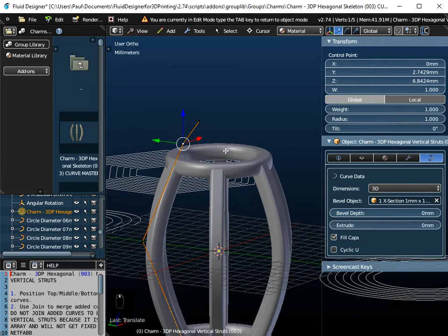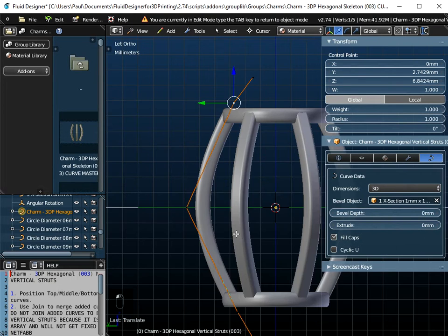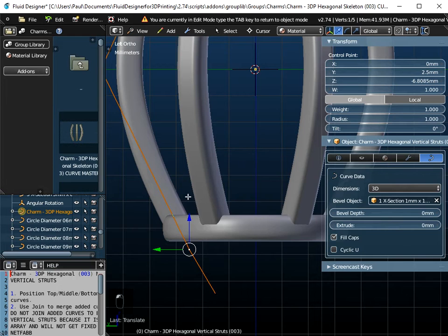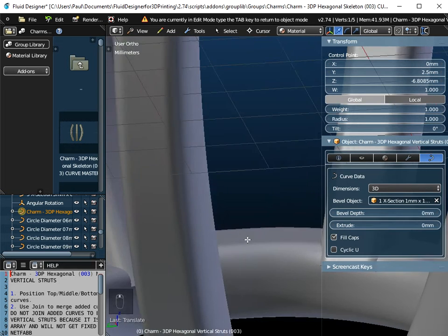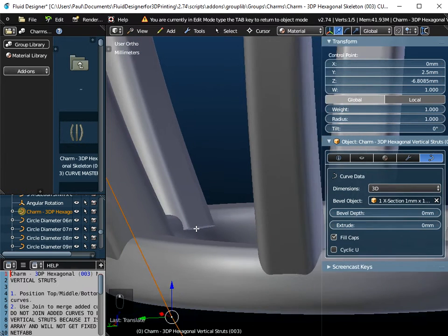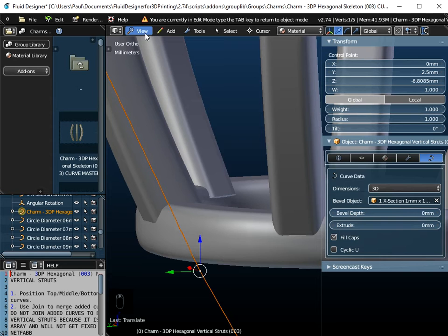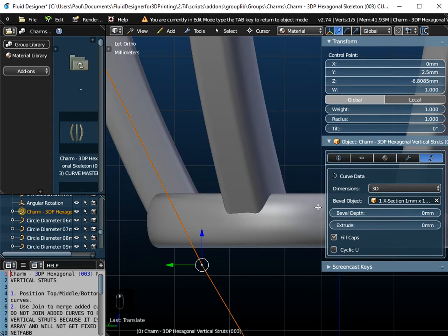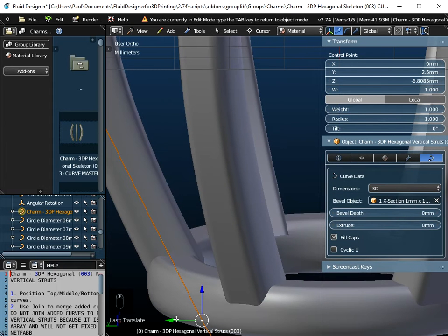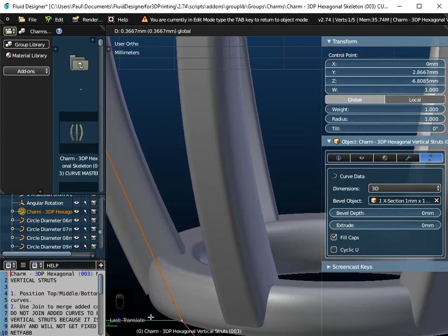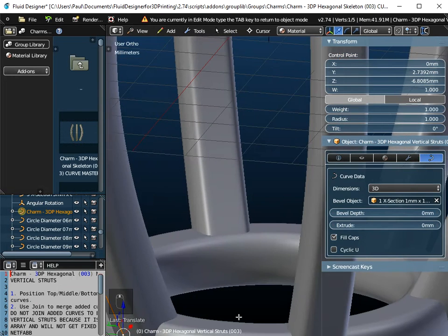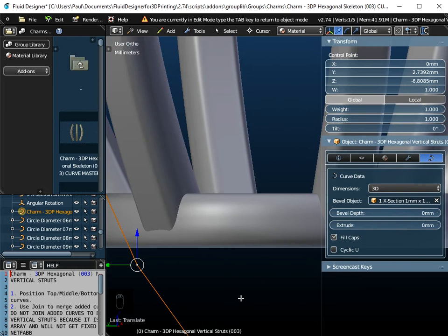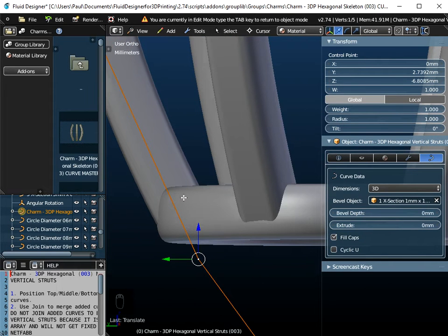So you will need to readjust that. So if I view from the left again, I've probably got the same problem at the bottom. You can see, if you're looking closely, it's just sticking out there at the bottom, so we just need to adjust that. So if we just go to View and Left view again, and I want to grab the y-axis this time, so if I pull the y across, you can see I pull that frame out, and you need to look here and on the inside as well, so you just need it all neatly inside the circle at the top and the bottom.